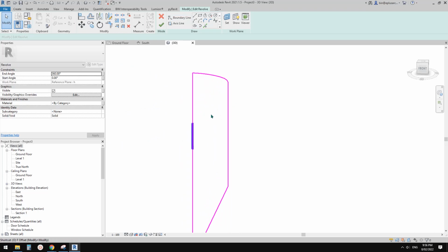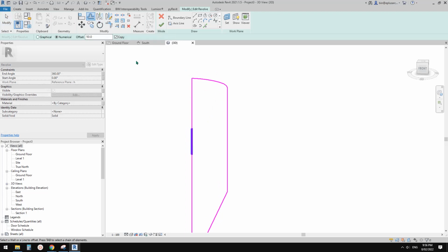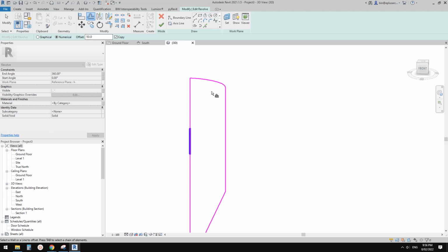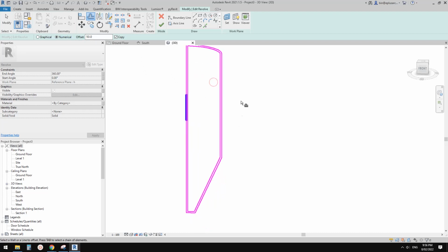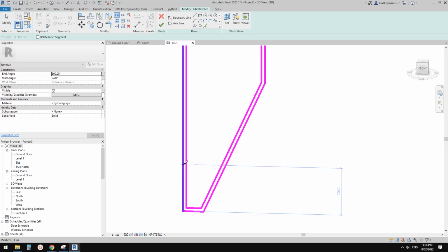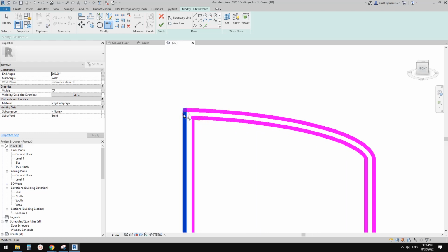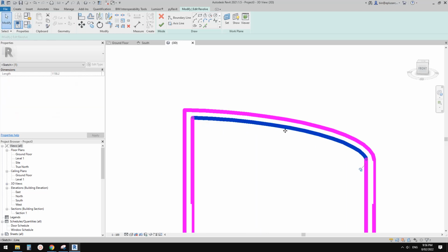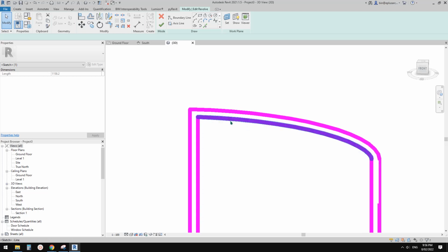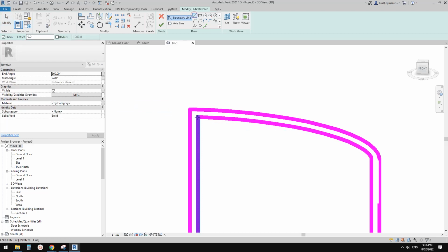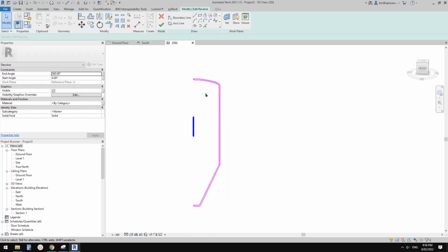And then we need a thickness. I'll use offset, OF, and just roughly 50 should be all right. Tab, and of course we trim and split this, so I can trim this, and also I'll trim here. Okay, it looks like it won't allow me to trim because this is not a perfect ellipse line. It's more like a spline. So maybe we can just draw this from here to here, and then we can trim. So delete this and finish this.